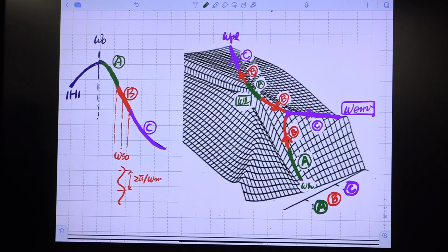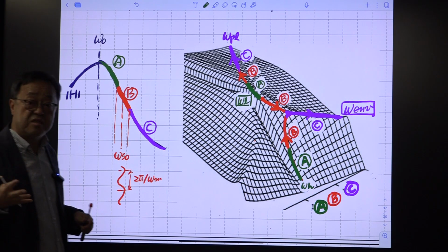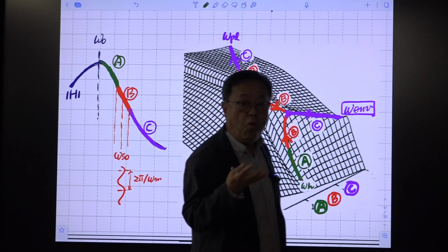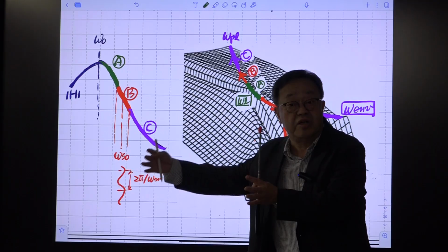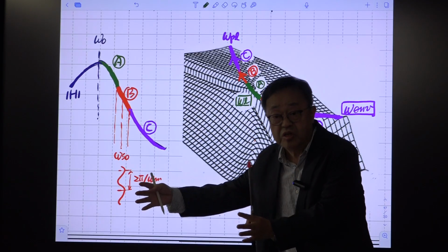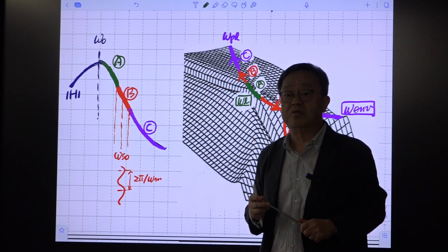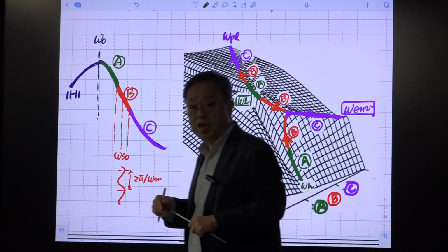and in the other region you have one double pole and only one dual pole. The dynamics will be different there. Okay? So you should select which point you design your compensation for. All right? And which is the worst case. If you design your compensation for the worst case, that should give the desired characteristics for the entire operational region in terms of stability and some other performance. Okay? That is the approach that will be taken.